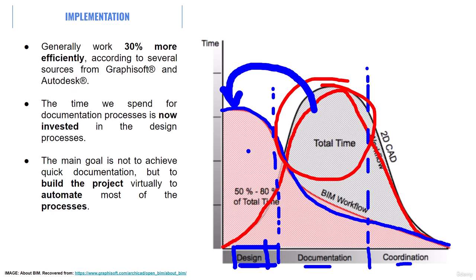And once the BIM model, the central BIM model is done, which includes the 3D geometry, which includes the 2D information, there are many automated processes that ArchiCAD and Revit will simplify, such as, for example, the ability to create cut sections and elevations in as quick as 5 seconds. You pretty much just draw a line and you instantly get your cut section, you instantly get your elevation, you instantly get all the planification tables, the schedules for doors, the schedules for windows. Pretty much all this documentation is done automatically with ArchiCAD and Revit based off the BIM model you currently generated.